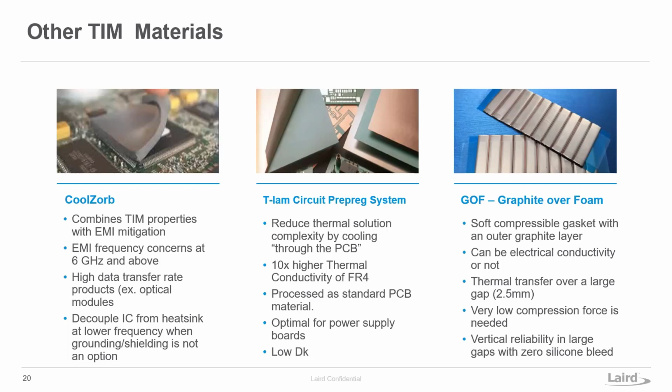You can use a metal substrate as a backer, aluminum or copper as a heatsink on the backside of the board, if your design permits that. And this prepreg has a thermal conductivity about 3, which puts it about 10 times the thermal performance of typical FR4.